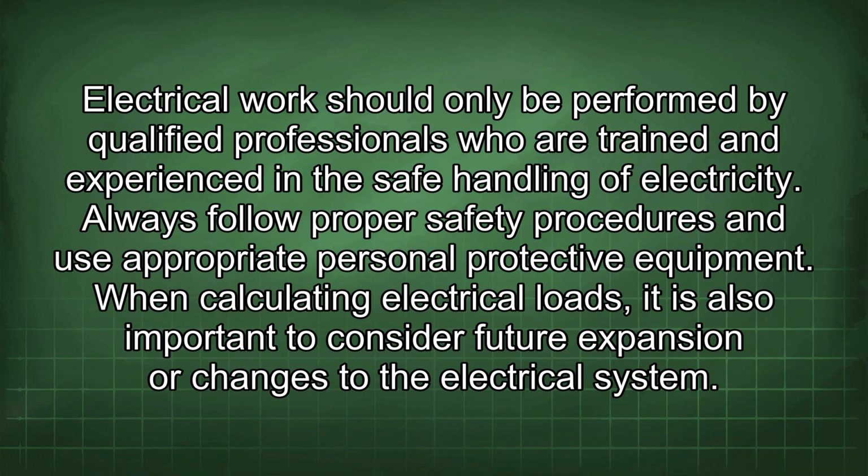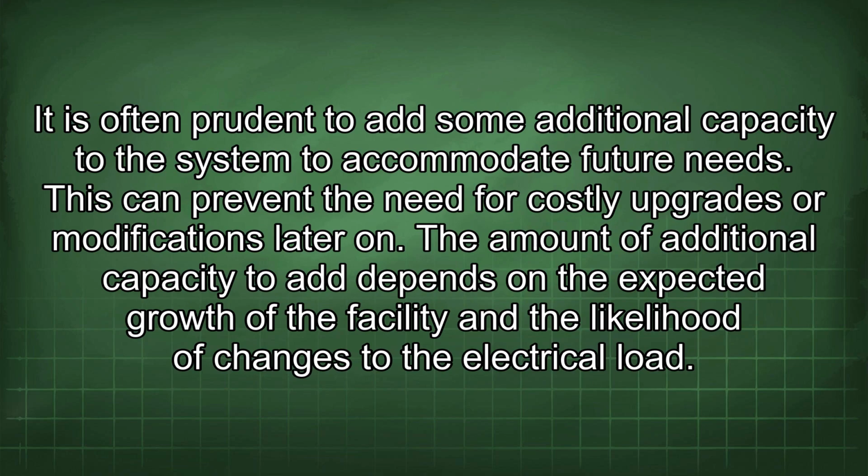When calculating electrical loads, it is also important to consider future expansion or changes to the electrical system. It is often prudent to add some additional capacity to the system to accommodate future needs. This can prevent the need for costly upgrades or modifications later on. The amount of additional capacity to add depends on the expected growth of the facility and the likelihood of changes to the electrical load.